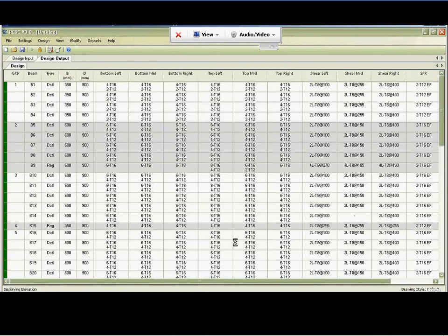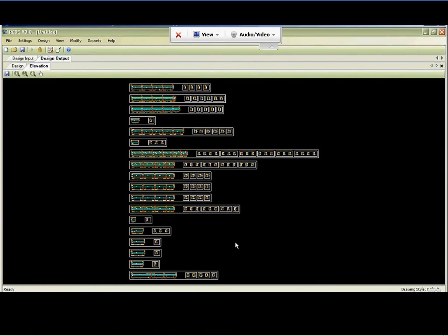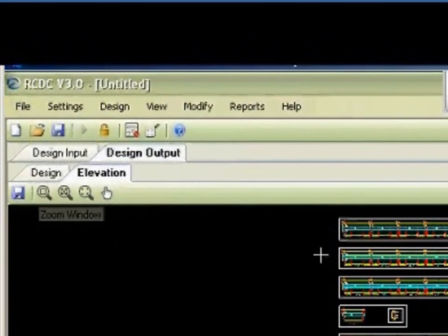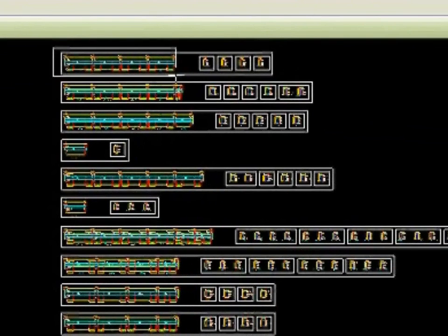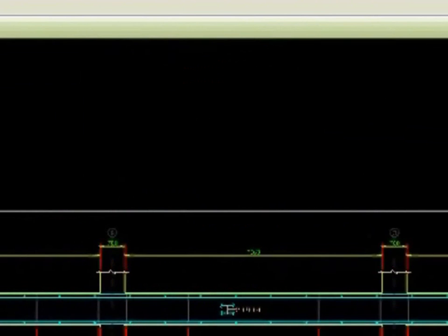What it does is scan the length of the beam, and wherever there is a change in cross section, it will give you a new section. So first section at the left end, and as you go along the beam, wherever and however many changes in the reinforcement happen, it will give you that many sections. So there you touch a button, and all 15-20 beams, elevations and cross sections are all drawn to scale, to size.